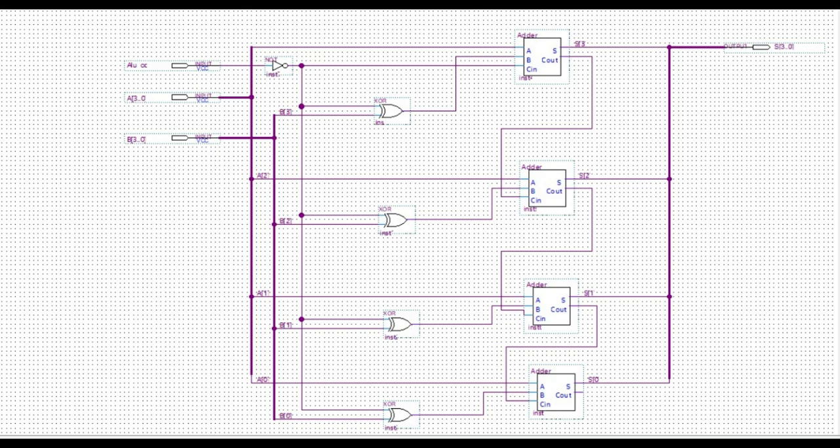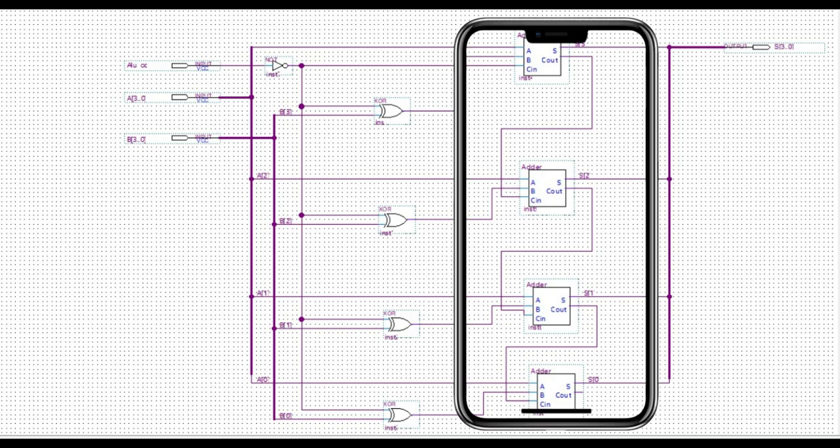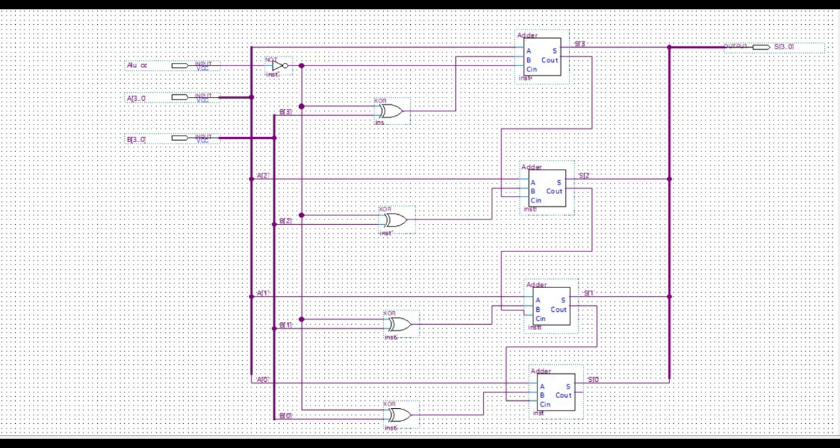We can proceed with the same method as previously with the multiplexer by exporting this to a block diagram. We can still create a customized adder and subtractor, but we make a 4-bit adder subtractor instead for fewer logic gates. We add 4 adders in our circuit, and since our data input is 4 bits, we name it A3 to 0. Then make sure to put a NOT gate, as this will turn 0 to 1 and 1 to 0 for the operations plus and minus.